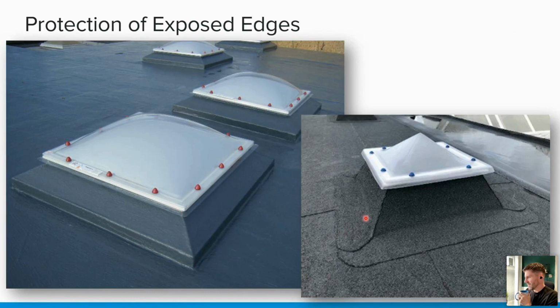Felt detail, like I said, take the felt up there, separate detailing sheet. So your cap sheet is going into the roof light here, and then you've got your underlay underneath here, and then you've got your flashing piece that goes over the top and is finished underneath there, and that exposed edge there is protected by the capping detail on that roof light.